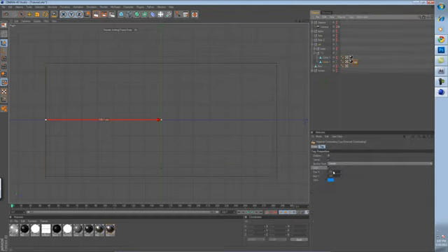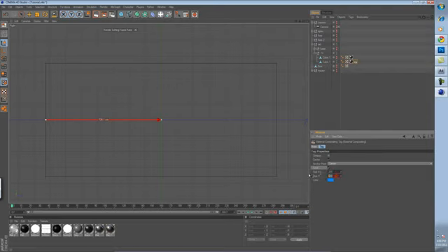So if I go over here, I can set the size Y. I have right now the y and the z axis showing. So I can say the length along the y axis was 712.2, because that's this height. And then the size X would be in this case the size z, and that would be 1452.2. And that'll be the horizontal measurement.